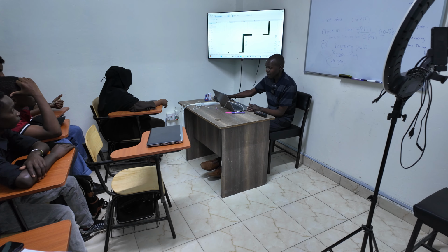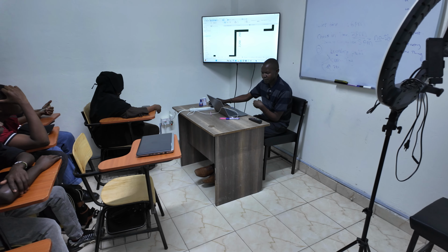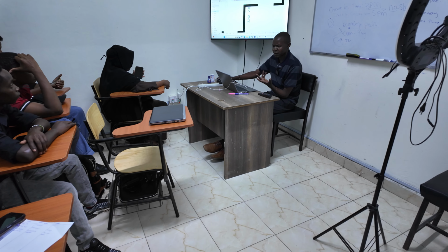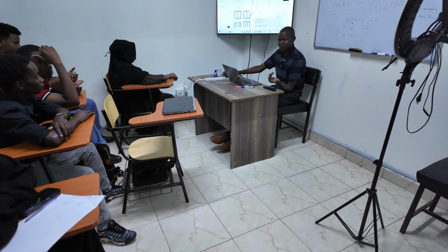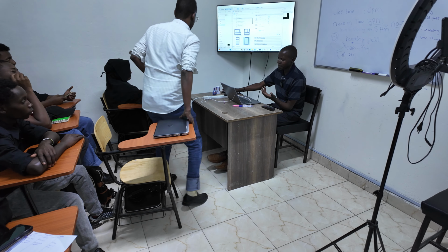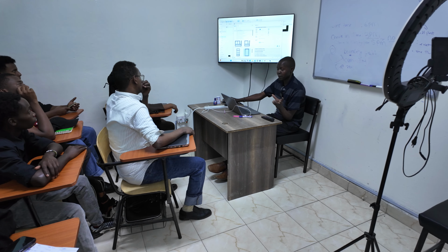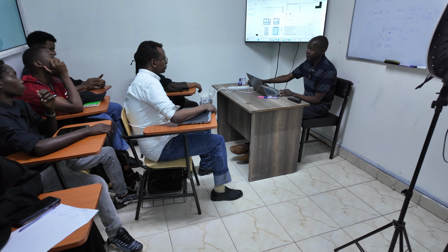So I just want to show you how you can change that. When you come to window, ArchiCAD also has those components of the window. You can see when you open, it gives you all the types of windows which you want. So you just pick your window, and then here we give the parameters of your window, like the width, height, and the sill height as well.